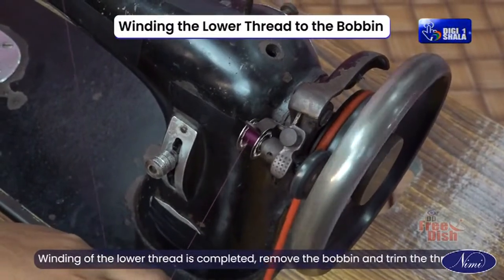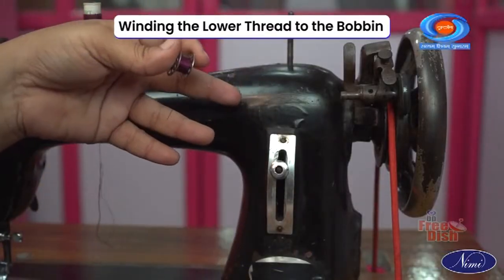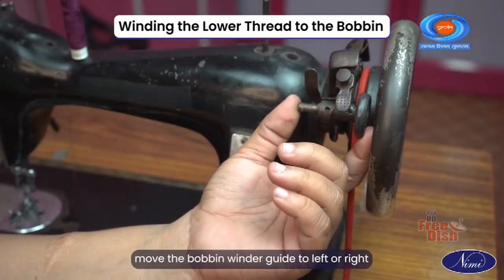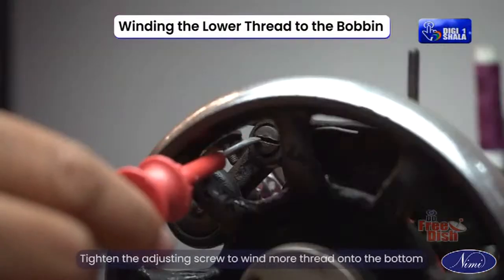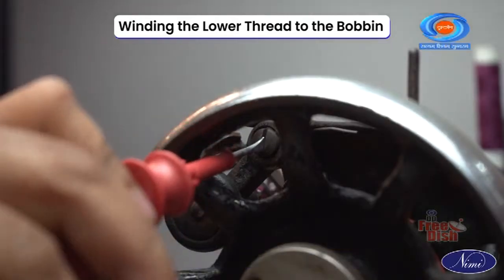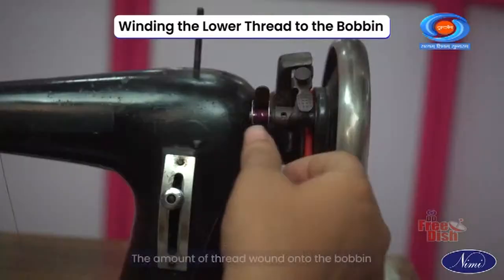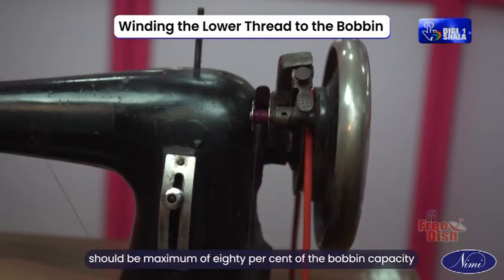Winding of the lower thread is completed. Remove the bobbin and trim the thread. Loosen the screw. If the thread cannot be wound on evenly, move the bobbin winder guide to left or right. Tighten the adjusting screw to wind more thread onto the bottom. The amount of thread wound onto the bobbin should be a maximum of 80% of the bobbin capacity.